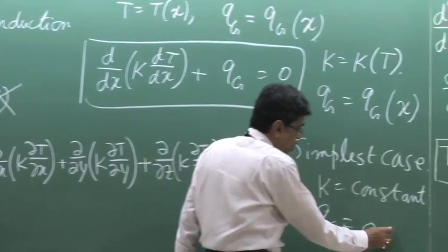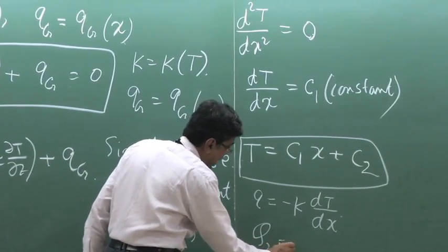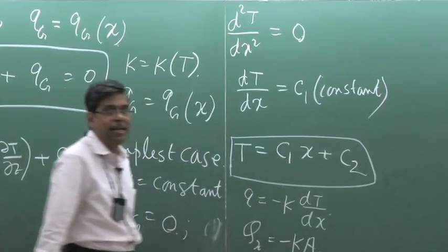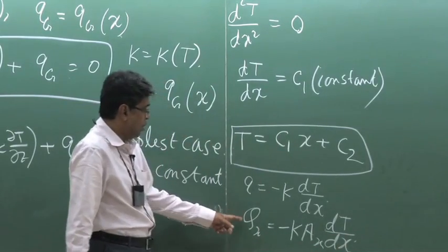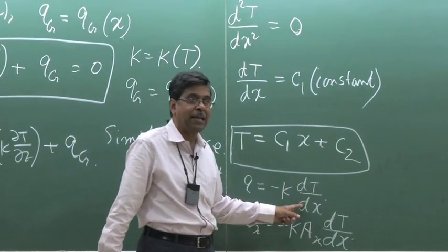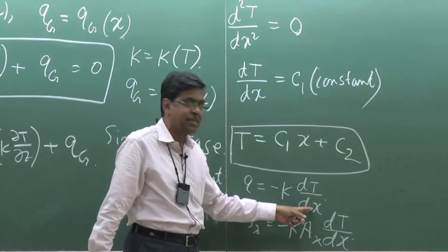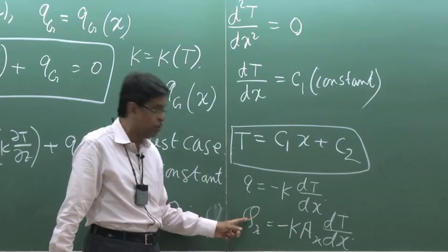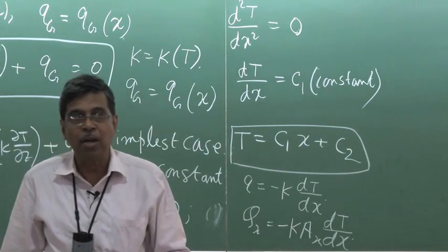At any point, if we consider an elemental area normal to the direction of x, that is the direction of heat flow, qx, the heat flux, is per unit area. And if we find the heat flux over an area, then we multiply with the area A. I write Ax, meaning the area normal to the x coordinate, but this x is not required because the heat flux is defined per unit area normal to the direction of heat flow, and heat flux is proportional to the temperature gradient along this direction. If these two pieces of information are there, I will find from common sense that since dT/dx is the temperature gradient, heat is flowing along the x direction. So, no area is to be multiplied here to find the total rate of heat transfer across an area A, which is nothing but the area normal to the x direction.